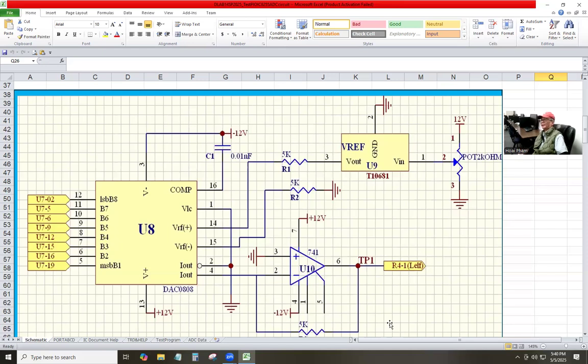And pin 14 here, what do you think the voltage is supposed to be? Zero. Correct. The thing is, 10 volt divided by 5K, that's why you get 2 milliamp. That will make the IC work.